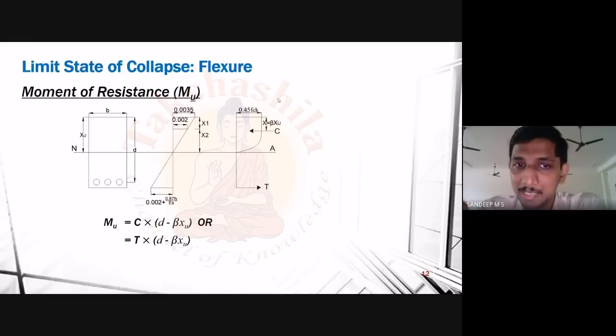And please keep in mind that we are now dealing with the under reinforced section. So when we have a load, the yielding of steel will start at a lower load. Please keep that in mind. Now I am just increasing my load from 0 to a higher load. Let us assume that 50 kilonewton is needed to produce the yield strain in steel. And since we have an under reinforced section, for making the yield strain in concrete, in comparison to steel, we will require a higher value of load. So for the sake of this example, I am assuming that the yield strain can be produced in steel with a load of 50 kilonewton.